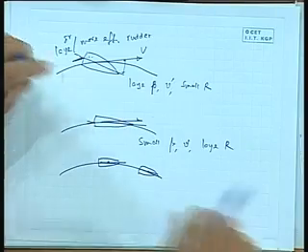If it did not have a drift angle, you can do that, provided, as you do in a maneuver test, because you are holding it by something else and turning it. On its own, by rudder, it cannot turn if it does not have a drift angle, which is not like a car. That means when it is turning, its x axis and the direction of velocity are not the same. You see the point, which is not the case in a car. When you are turning, the car follows that line. Here it is not so.